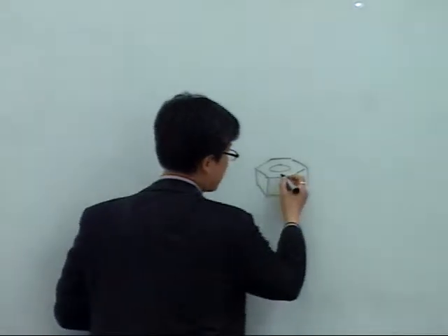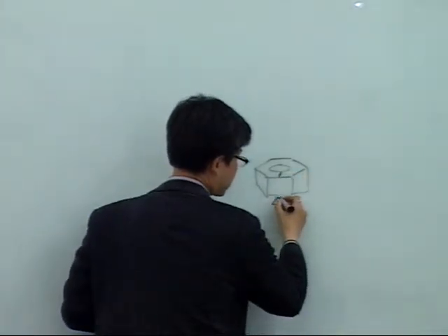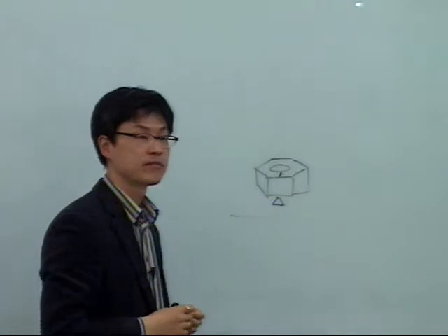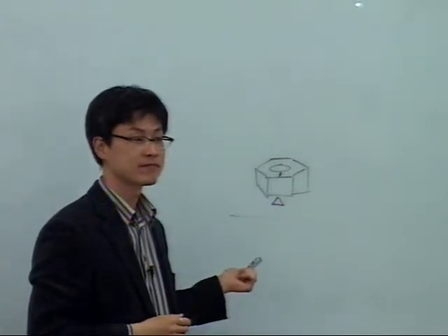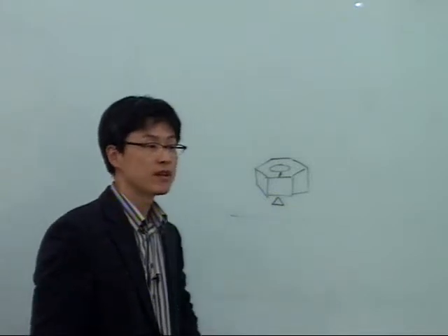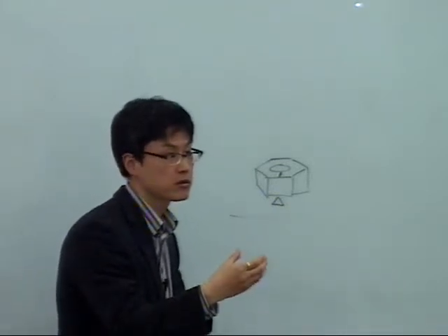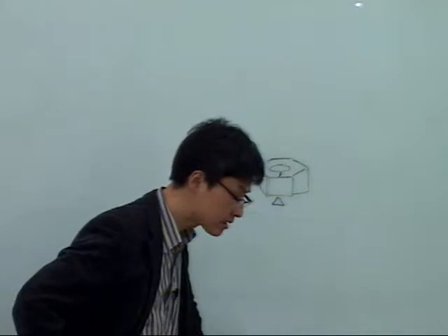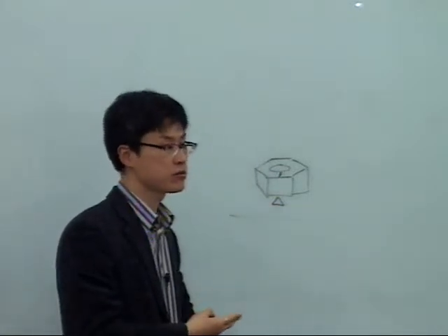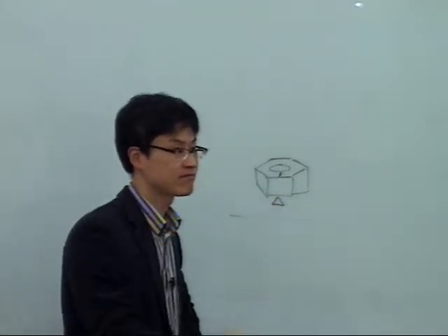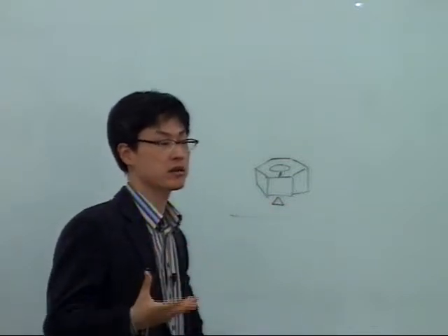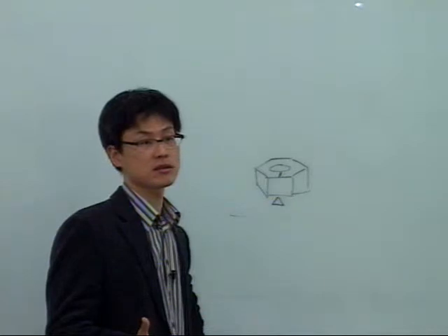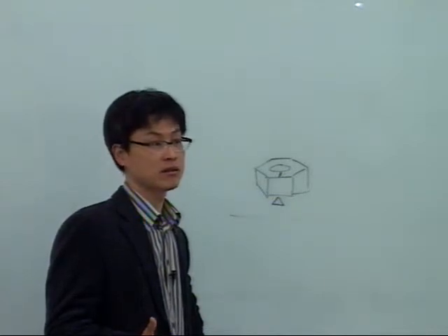And sometimes they color it like this. Why? If it is loosened, anybody can see and tell this bolt is loosened and it needs securing. It automatically, visually tells its current status, right?